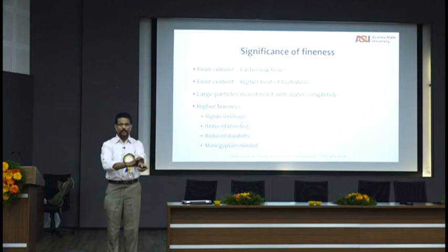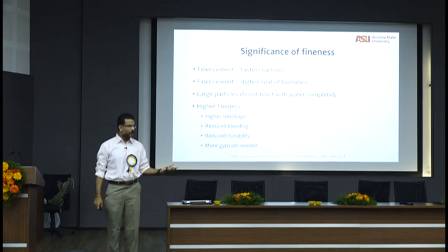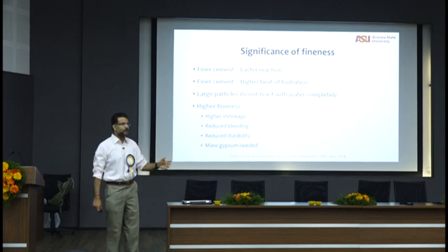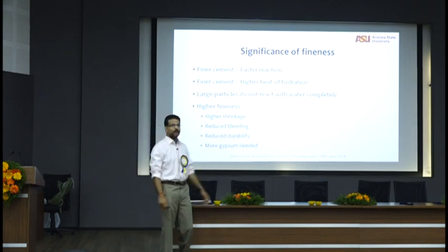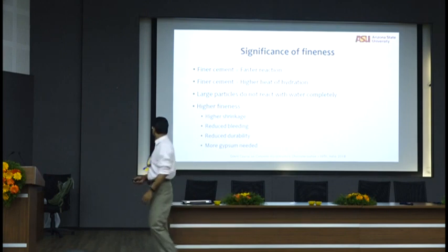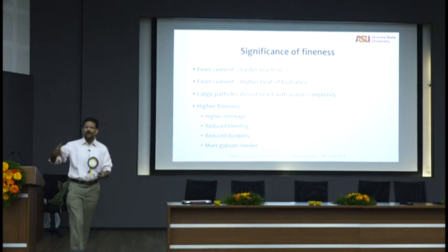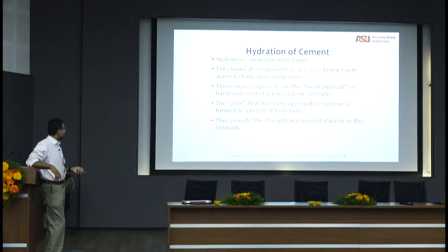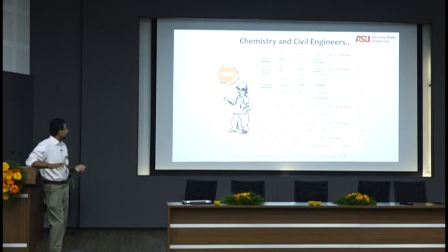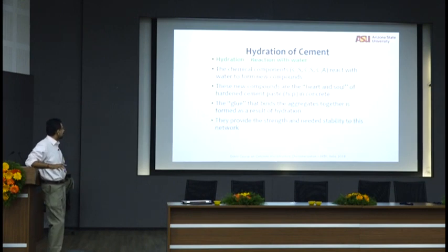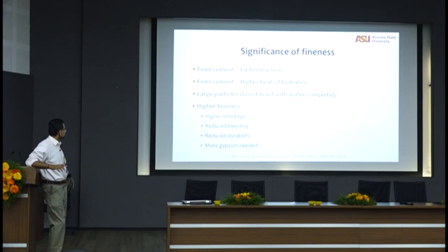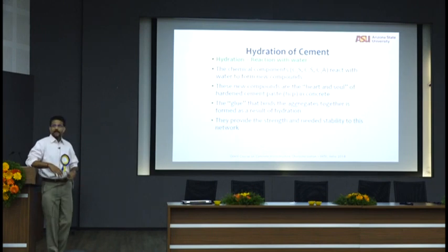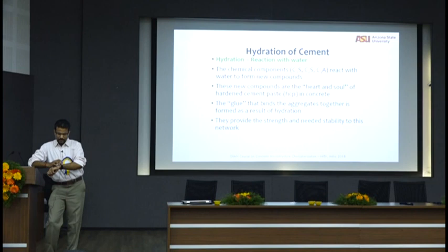I'll show you some examples of what we have done with inert limestone powder, where you add limestone and let the cement hydrate, and the limestone acts as what we call nucleation sites for cement hydration. I'll show you that probably tomorrow. So there are a lot of ways of controlling that. Again, that's why I said it's a designed product rather than a random sequence of things.